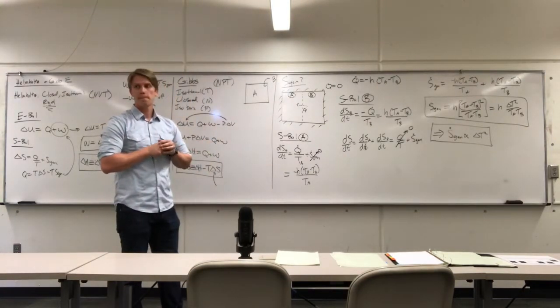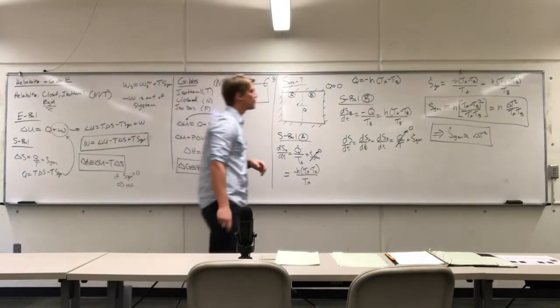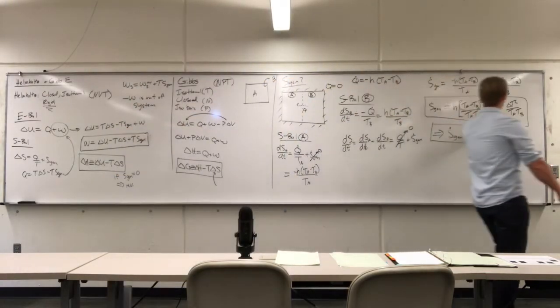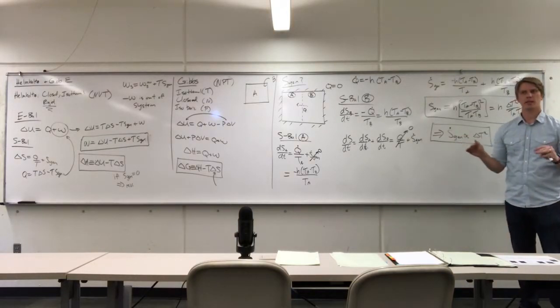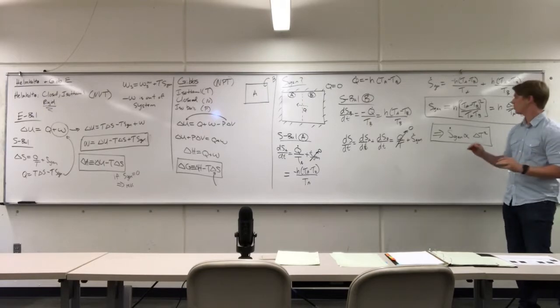The lowercase h is the convective heat transfer coefficient, right? Yeah, not necessarily convective, just some heat transfer coefficient. I don't want to necessarily ascribe any particular mechanism to it. So, what this means, and this is something to keep in mind for all of the universe: anytime we have any gradient, entropy is being generated. This is what the conclusion of this one here is.